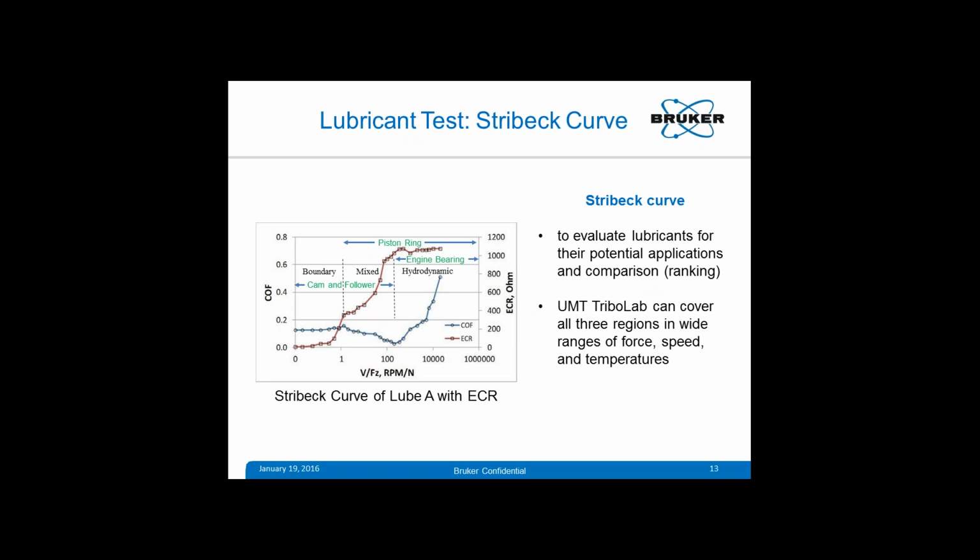Lubricant test is basically done by obtaining a Stribeck curve. Let me explain for those who would like to know more about the Stribeck curve. A Stribeck curve is basically a plot of COF, coefficient of friction, versus speed divided by load, the normal force. And it plots for a particular lubricant. You see in this case we had gone over about seven orders of magnitude. And you see this curve, this is actually the Stribeck curve.